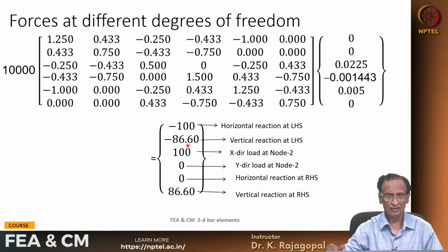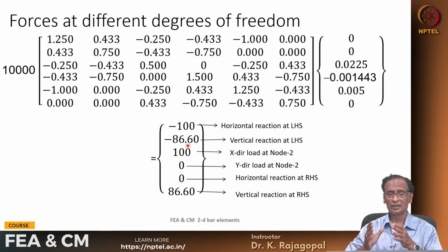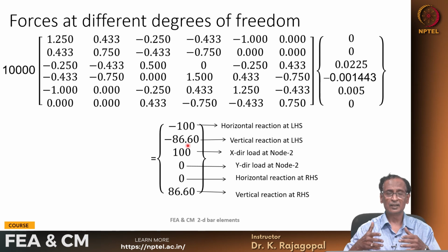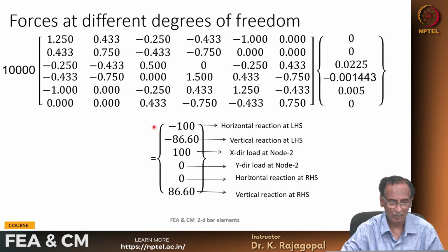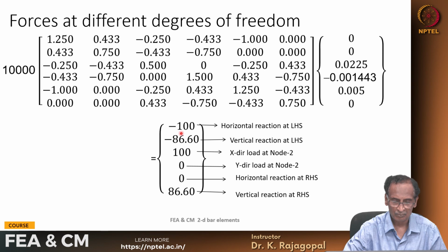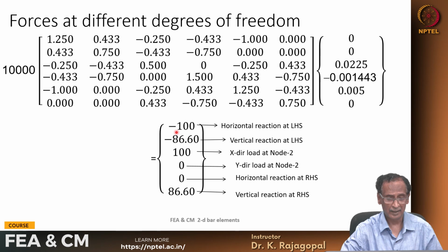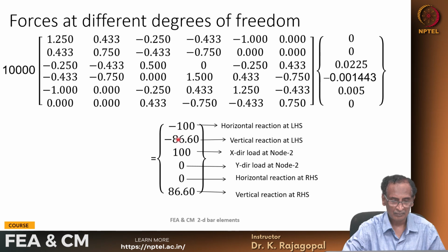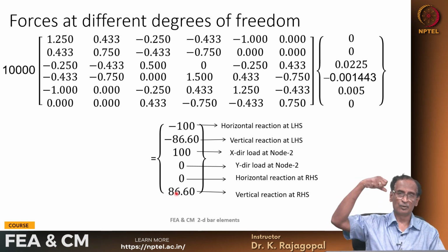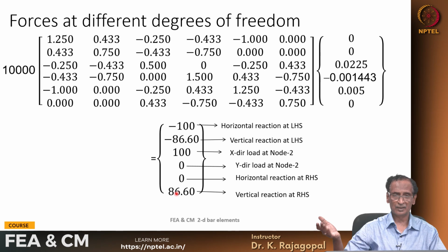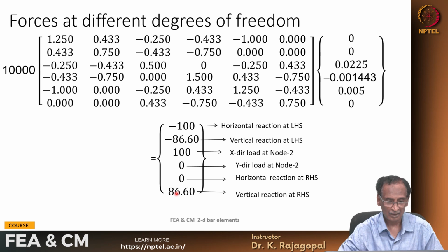And actually we require these reaction forces at the supports so that we can design the foundation. So our foundation should be able to comfortably resist a force of 100 in the horizontal direction and a force of 86.6 in the vertical direction. Okay. And this is downward acting, this is upward acting. So obviously if you have an upward acting force, we will go in for a pile foundation, like a tension pile, okay, or something like this, or a ground anchor to support this.